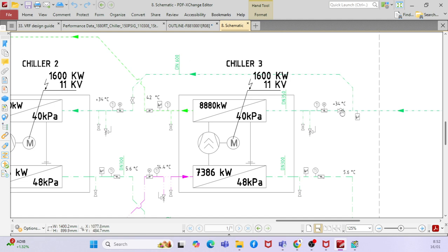So, irrespective of air cooled or water cooled chiller, there is always the refrigerant portion that is involved in the chiller. Yes, it's correct. Just that in the case of air, whatever heat is being rejected from the refrigerant just goes out and gets rejected via air. Whereas for the water case, we have the water that basically does all of the absorbing of the heat and rejecting it outside.